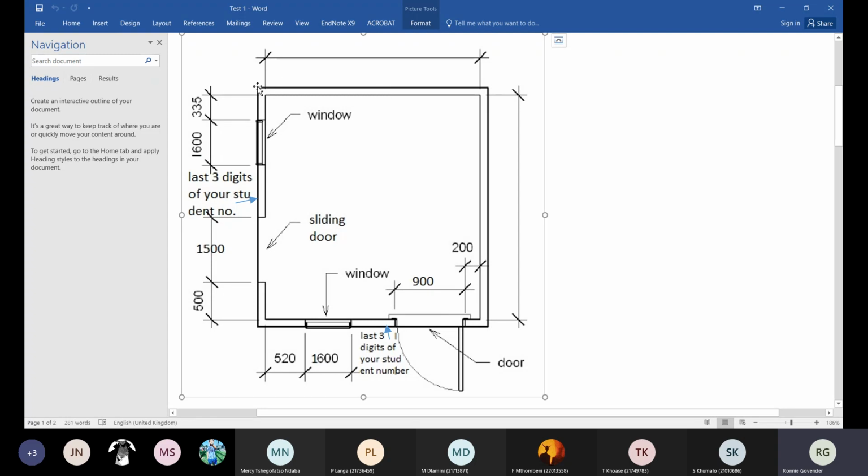The gable is half base times height, as we told you. I'm just going to call that side, which is the longer side, the length, and we'll call that the breadth, because it varies for each one of us. So it would have been half the breadth times the height, which was 1.2. And I got 2 of those, so times 2. So the halves would have actually cancelled off. So it would have just been the breadth times the height. That would have given us the gable.